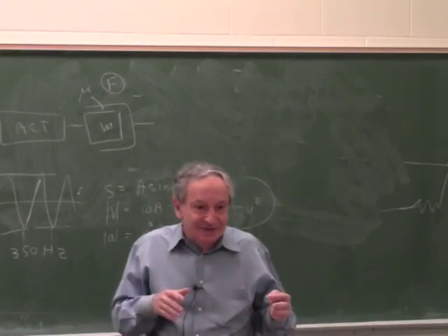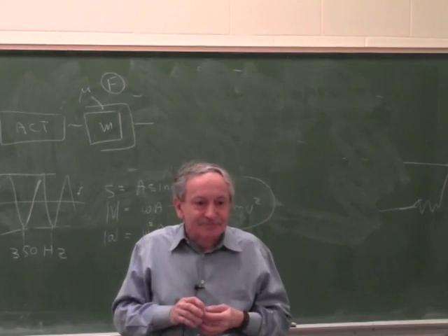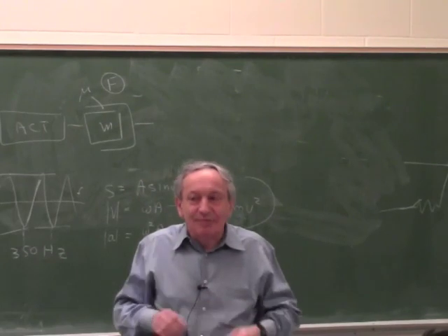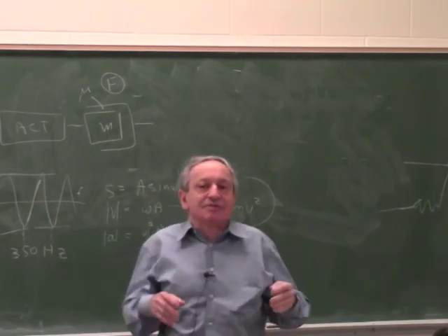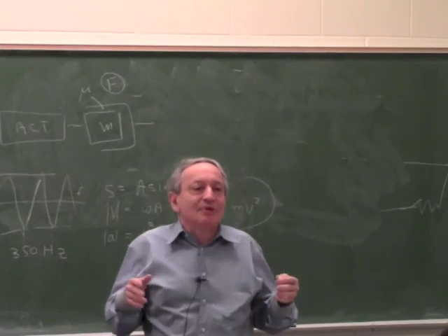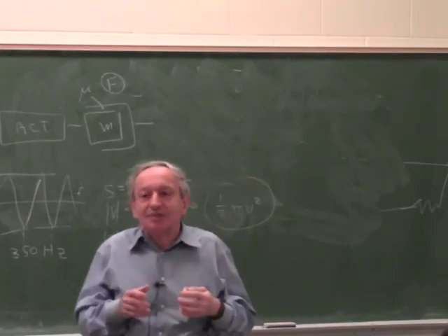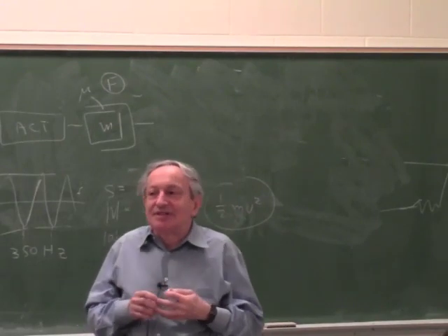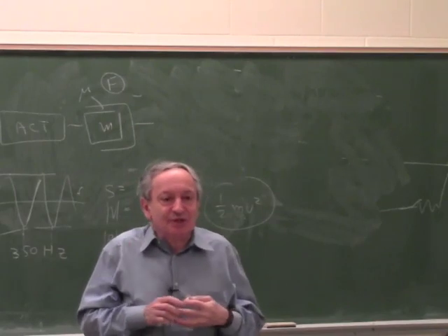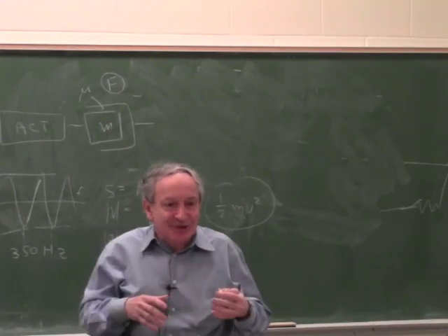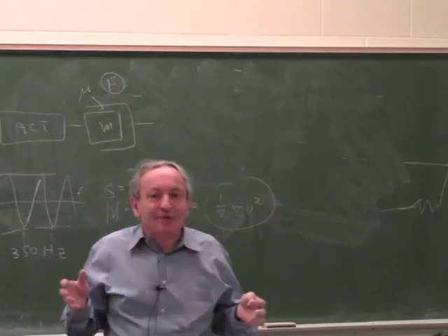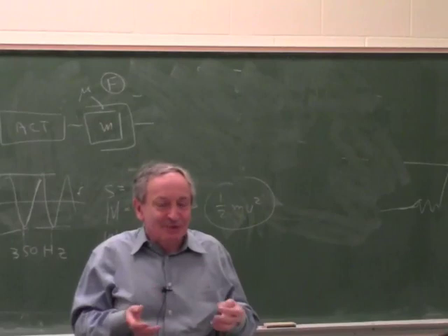To initially put the initial energy in the system, don't you need the power that you calculate from the beginning? Yeah, but that's just when you start. You need initially the power to accelerate, but in terms of overall, let's talk about things like heat dissipation on the amplifier. So you do need the peak power to be able to move, but the total power in terms of heating losses, if it's recoverable, it's much less.